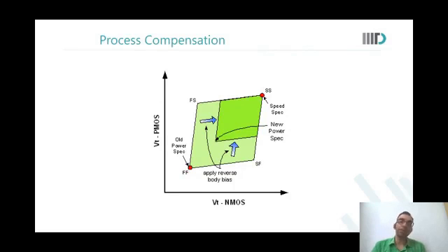However, in advanced technologies like FD-SOI, fully depleted SOI, there is no junction in the source and drain region. There is simply a buried oxide. So since there is no junction, there is no concept of junction leakage per se, and junction leakage cannot increase.